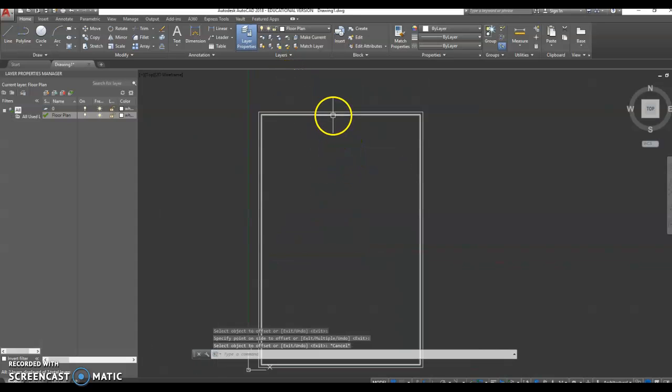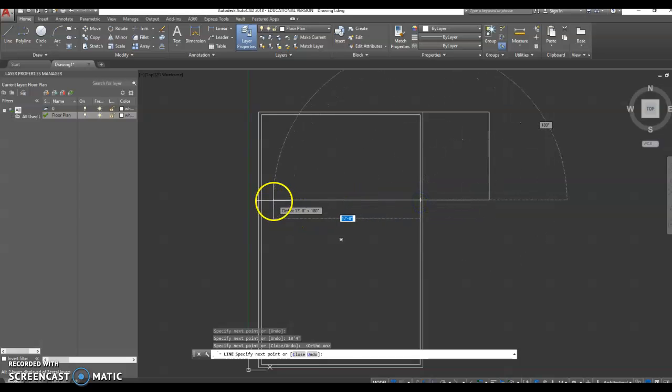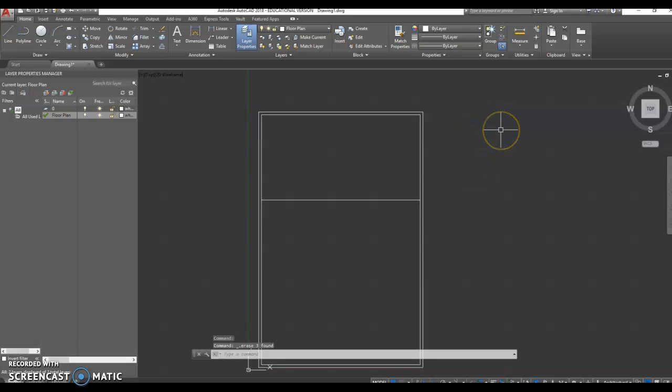Now, I want to take this. Something we do when we're doing floor plans is sometimes we have to do temporary lines. So I'm going to come down 10 feet. That's 10 apostrophe, 4 inches, enter. Then make sure my ortho's on, F8, function 8. I'm going to come to that inside line, then I'm going to carry it across, left click, and I'm going to get rid of this. This was temporary, I don't want it anymore. So I've got a 10-foot space here.